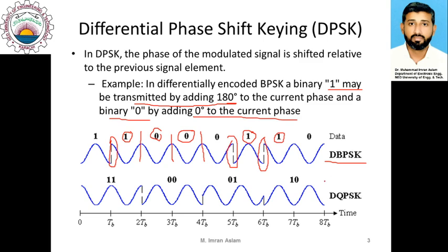Similar information can be encoded in higher-ary systems, M-ary systems. For example, for a 4-ary system, if you have a differential QPSK system, in that case again the information would be encoded by a phase change, but now there will be 4 possibilities of phase changes. Say for example, 1 is represented by no phase change, so you do not see any phase change for 1. When it is 0 you would see a phase change of 180 degrees. So a 180 degree phase change represents that the next 2 bits are 0.